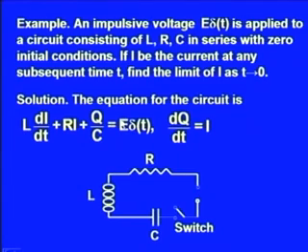So, if q is the charge on the condenser at time t and I denotes the current in the circuit at time t, then dq by dt is equal to I, and the voltages developed across the inductance, resistance and capacitance are given by L di by dt, R i, and q by C, which sum to the electromotive source provided in the given circuit.